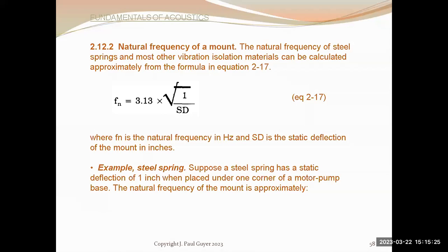And when the fan is running and vibrating, the spring isolators bounce up and down a little bit and isolate the building structure, the floor deck, the beams, and columns from the oscillations that are produced by the rotating fan.